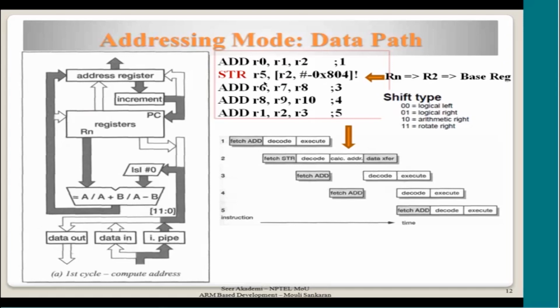I will explain what the corrective action is later, but assume the processor can start the same str instruction again. In that case, what will happen? R2 would have been already updated. Then you won't be doing what you wanted to do, right? The processor won't be doing what you intended.